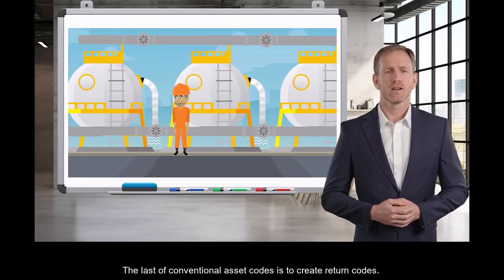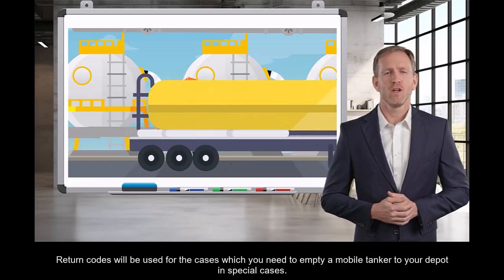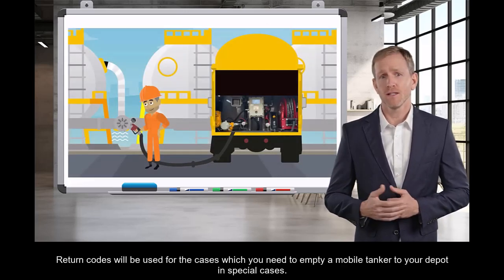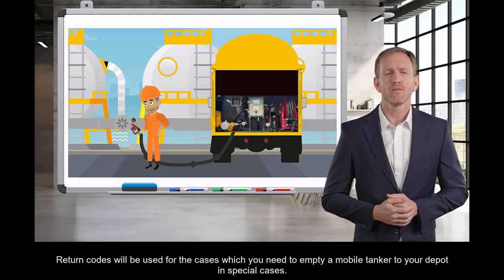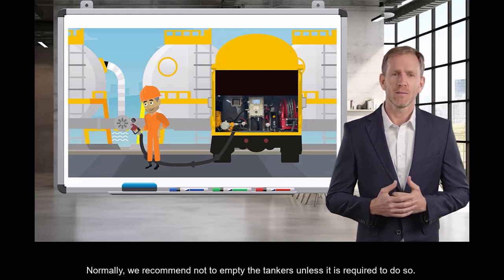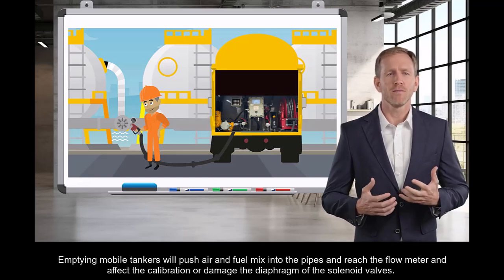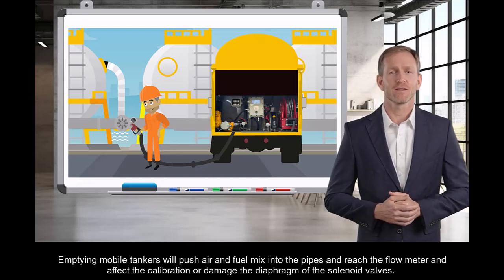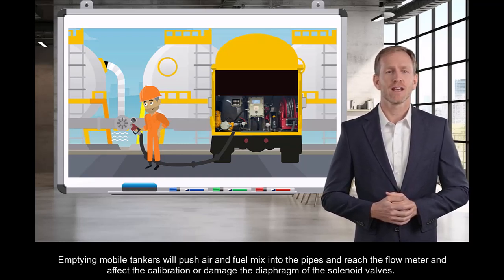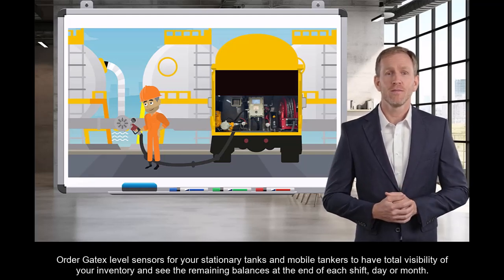The last of the conventional asset codes is to create return codes. Return codes will be used for the cases where you need to empty a mobile tanker to your depot in special cases. Normally, we recommend not to empty the tankers unless it is required to do so. Emptying mobile tankers will push an air and fuel mix into the pipes and reach the flow meter and affect the calibration or damage the diaphragm of the solenoid valves.